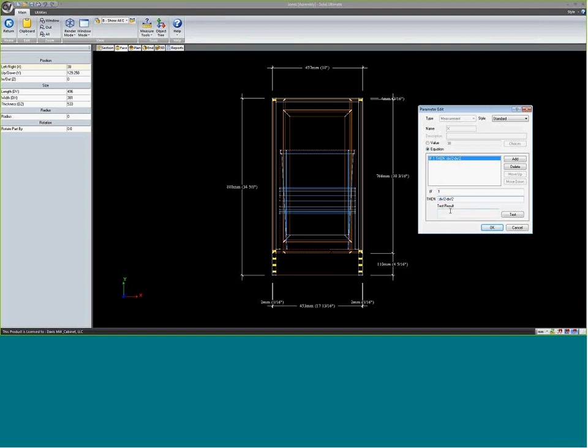The colon represents going up the object tree one step. So I want to go up one step from the trash bin. So I'm saying the width of the cabinet, the colon dx, divided by 2 is half of the width of this cabinet, minus the dx, or the width of the trash bin, divided by 2.